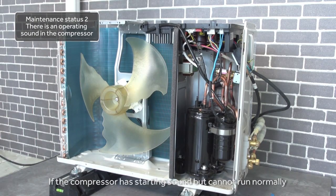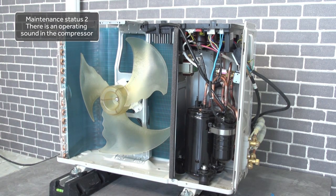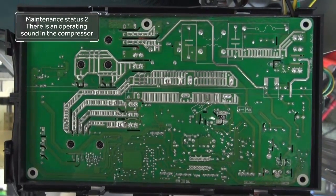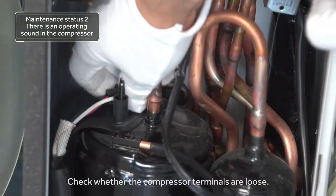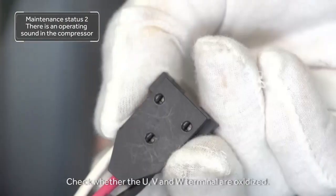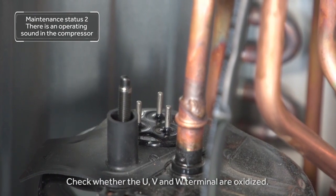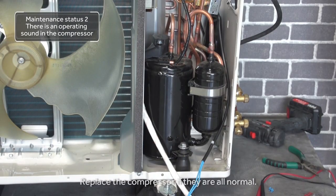If the compressor has starting sound but cannot run normally, and the LED 1 flashes twice, check whether the compressor terminals are loose. Check whether the U, V, and W terminals are oxidized. Replace the compressor if they are all normal.